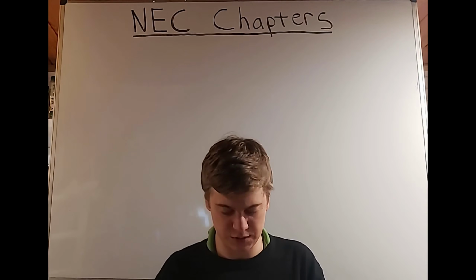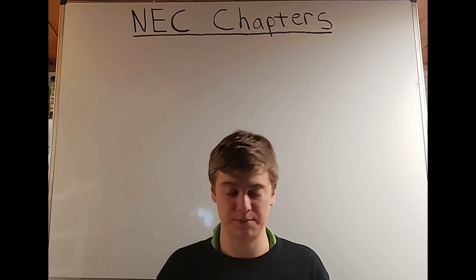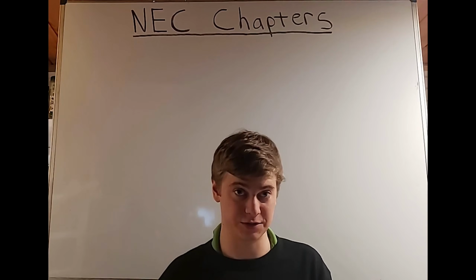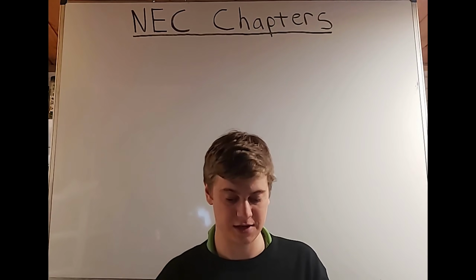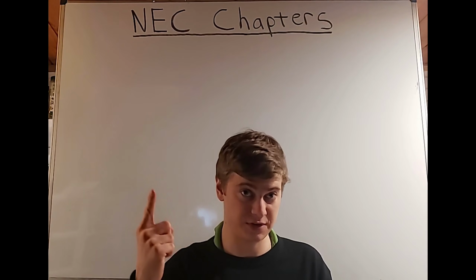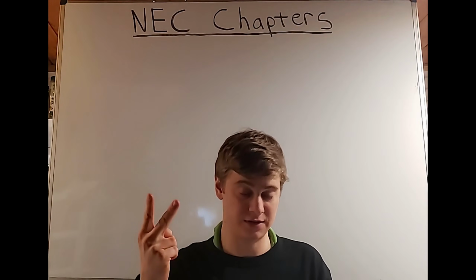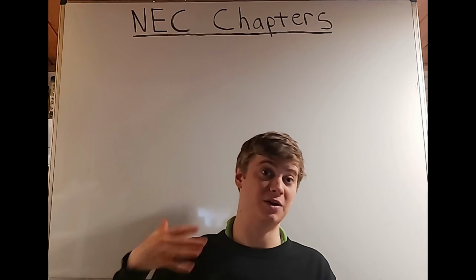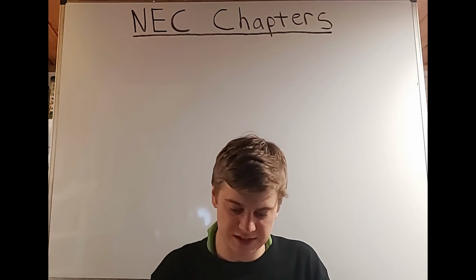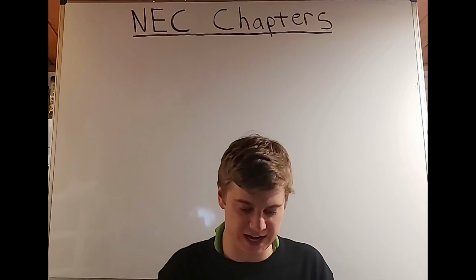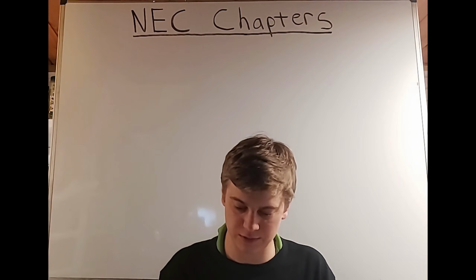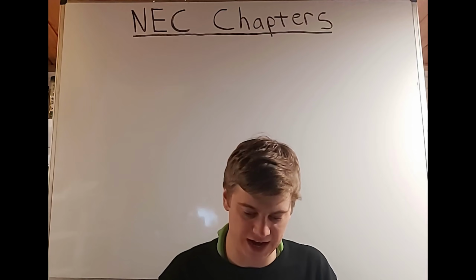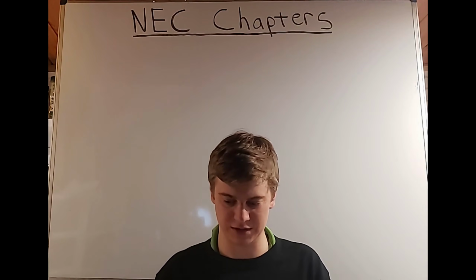We move on to Annex C. This is very important. You're going to use this table when you have multiple conductors that are all the same size. So you're going to know the type of conductor you're working with, the gauge of conductor that it is, and then you also know the number, and they're going to be all the same size. So let's say we have 16 number 12 THHN conductors, and we want to fit that inside an EMT conduit. We see that would fit a 1/2 inch EMT conduit here in Annex C.